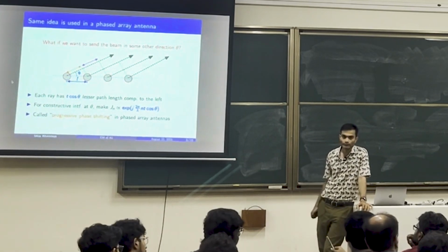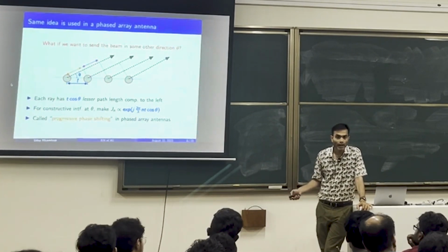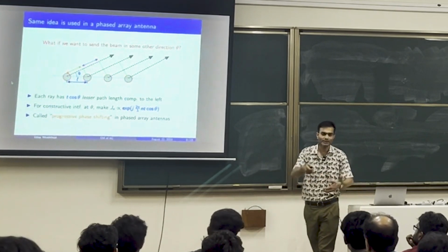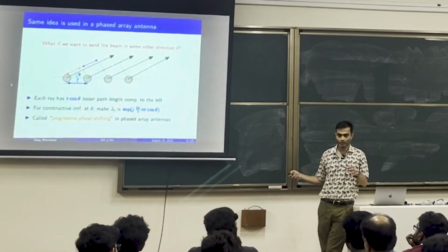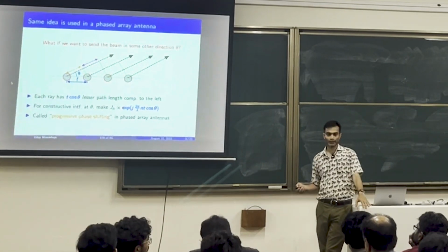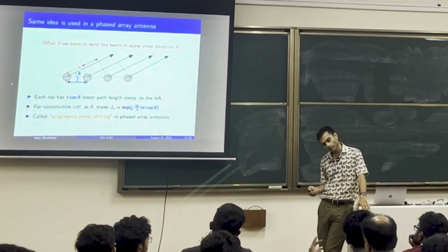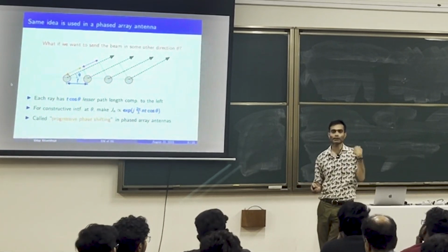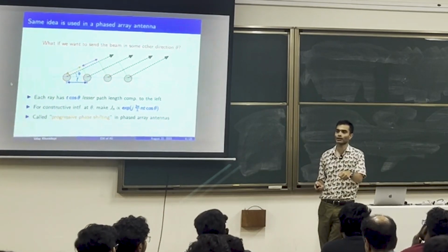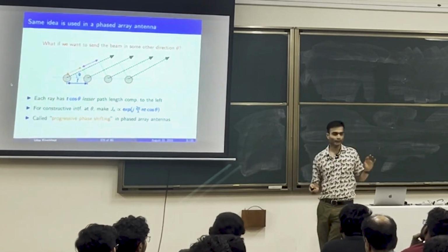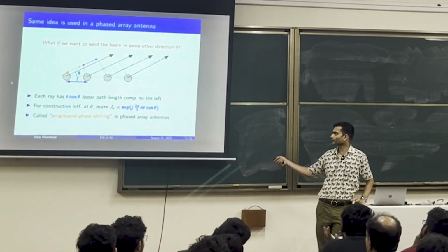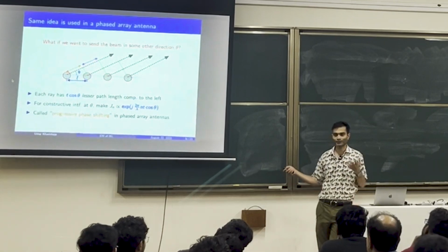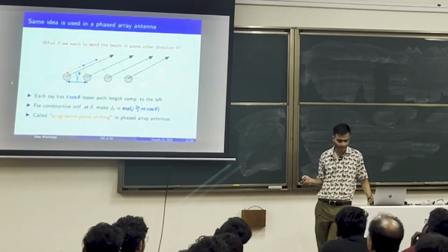That's a complex number. It is proportional to the current, and there are some constants which depend on the antenna dimensions and so on. Those are constants, but you're changing the phase of the current, and that will dictate the phase of the electric field. It's a simple concept in antennas: field is proportional to current. If I double the current, I double the field. If I add a phase to the current, I'm adding a phase to the field. Really simple. There are a whole bunch of proportionality constants we don't need to worry about. If I choose a patch antenna instead of a horn antenna, that constant is different. We don't care. The concept is phase.